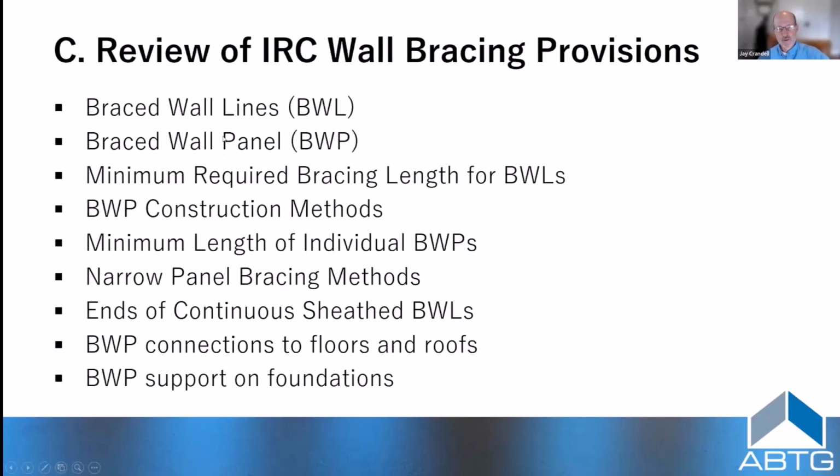So we're going to go down through the nitty gritty of some of the wall bracing stuff. We'll look at, what is a braced wall line? That's sort of the main element where bracing goes, and the wall lines of the building that are declared to be required to be braced wall lines. There's flexibility, and there's an art to what you call braced wall lines. You may need an interior wall line, you may not.